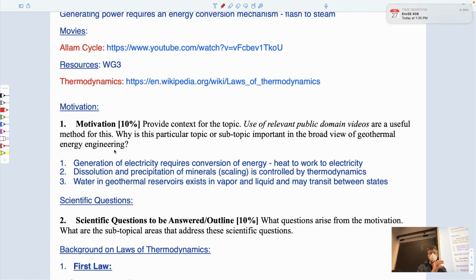But both in geothermal heat pump systems and also in binary systems, if you flash to steam and you bring the temperature of your water back to 100 degrees centigrade, you can still get electrical energy out of the difference in temperature between 100 centigrade and 40 centigrade if you have a fluid that will change from liquid to vapor at 40 degrees centigrade. So you take the 100 degrees, you transfer it to this heat transfer fluid that vaporizes at 40. It generates electricity, is condensed back to below 40, and then used in a system.